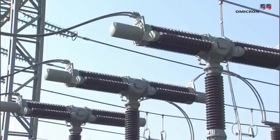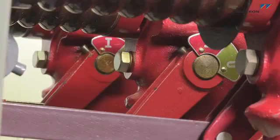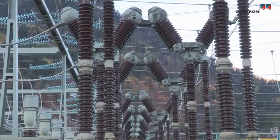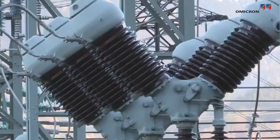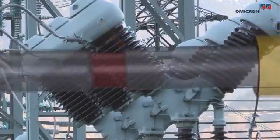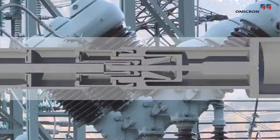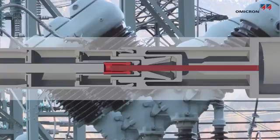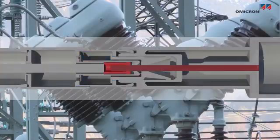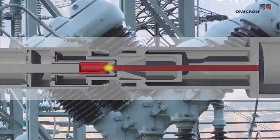Different circuit breaker technologies are in use, depending on voltage level, application, and the age of their design. Current interruption takes place in interrupter chambers containing air, oil, SF6, or a vacuum. Circuit breakers may use multiple contact systems consisting of main contacts and arcing contacts. The main contacts allow operating current to flow with minimal losses, while arcing contacts can break short circuit currents with minimal arcing erosion.